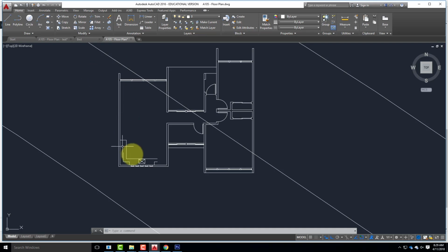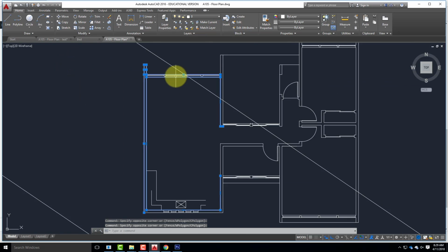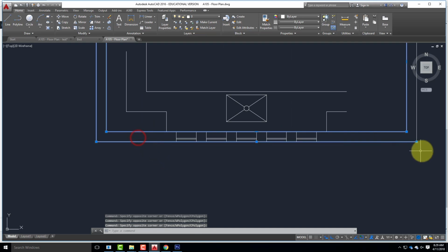I'm going to go through and select my walls. This takes a little bit of time, depending on how you drew it. As I'm working my way around, now we get to windows. I have a series of fixed pane windows here above the kitchen. These lines that divide the windows, because of where we're cutting the floor plan, which is 4 feet above the ground, we're cutting through the windows. Therefore, we're going to include these on the wall layer. Even though technically they're windows, these dividing lines are going to be on the wall layer.